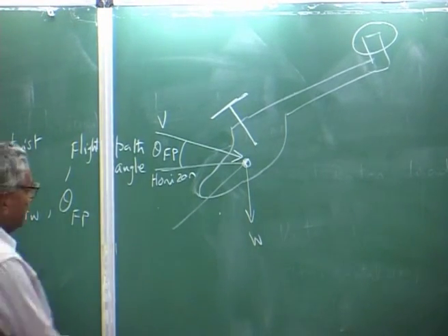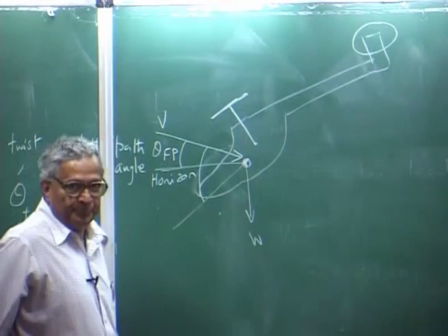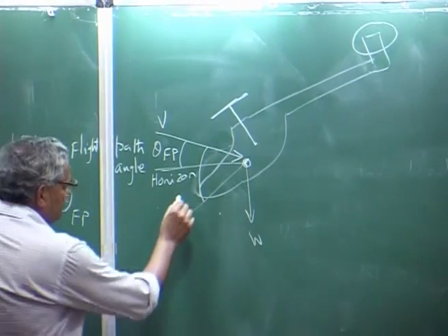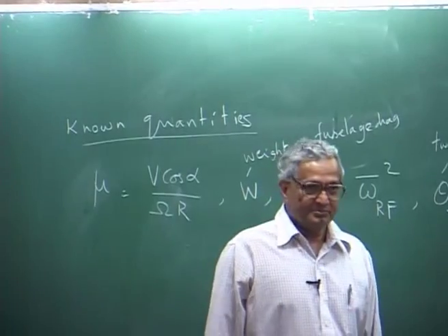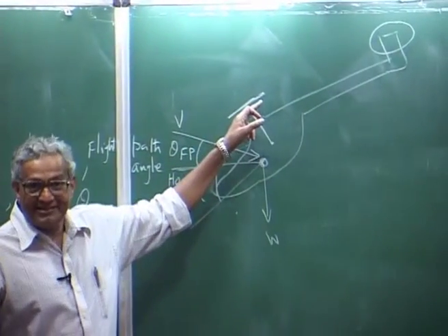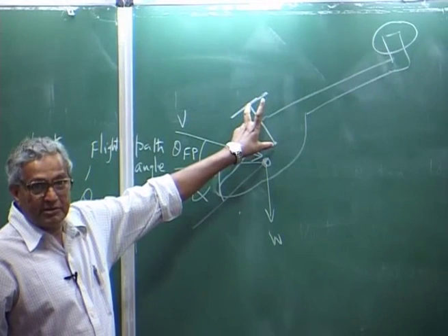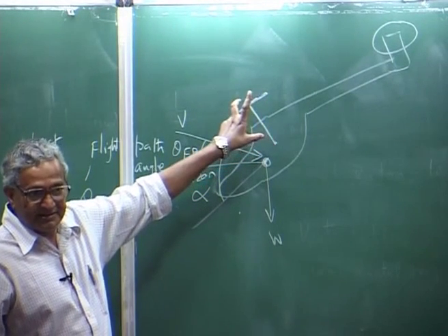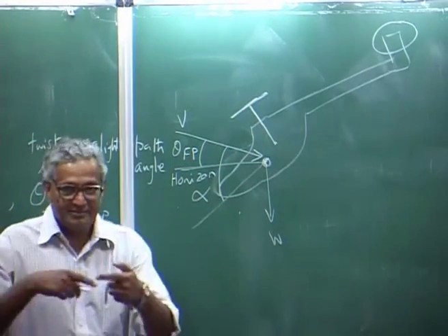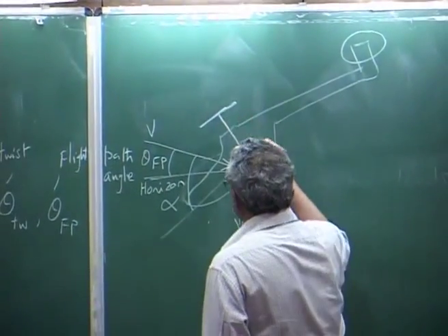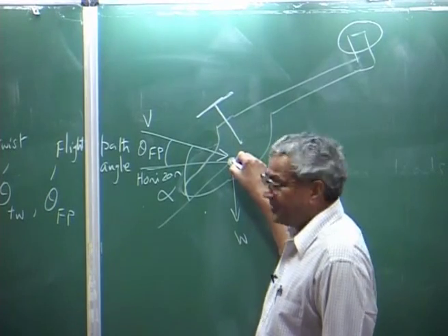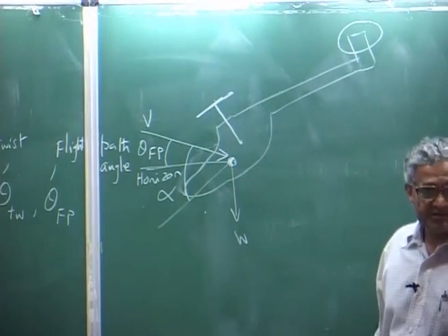If this can be 0 means you say level horizontal flight. Okay. And this angle I call it as alpha. Okay. That is the angle, because this is what is required. This alpha comes here, because we cosine alpha in the hub. Now, you may say this is perpendicular to, if the shaft is perpendicular to the body fixed coordinate system, then it is fine, because this will be 90 degree, because you can have fuselage axis system, and that will be same as hub axis system.